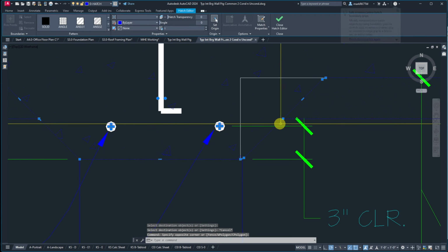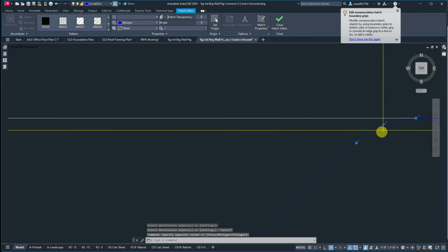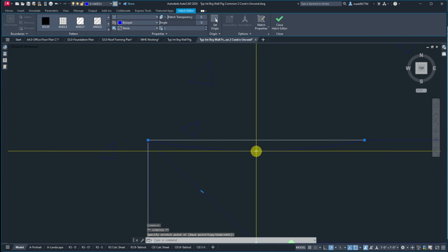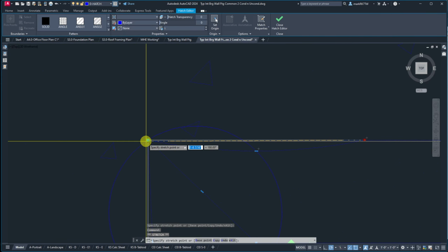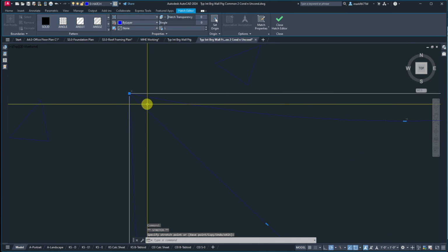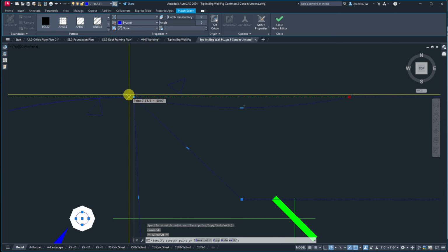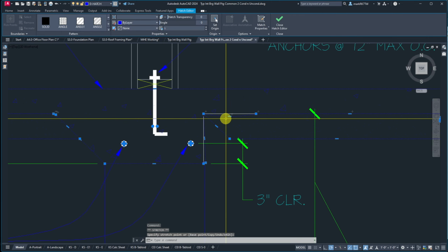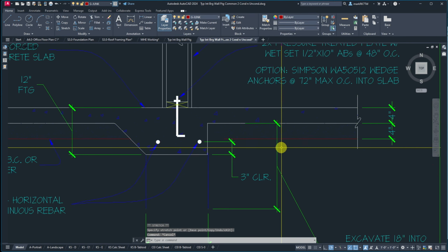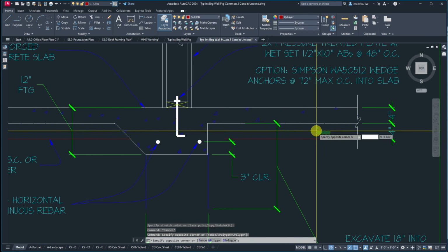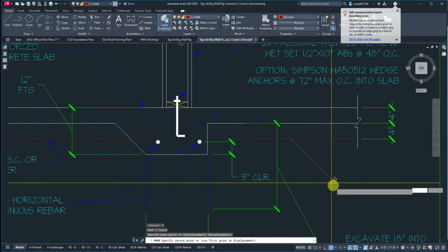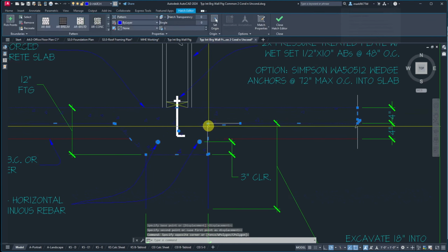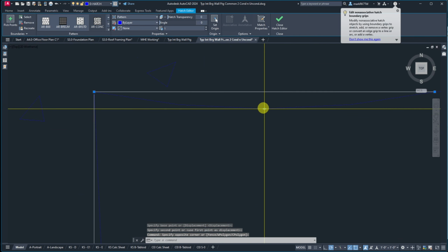Now let's see if we can edit this. Okay, it looks like it was actually made into a, see in the circle stuff, it may not allow me to stretch this. So if you can't get that to do what you want and get rid of that circle, see how it's not behaving, then just like I did with that other stuff, grab this type and move it. And that's why I keep these red lines here that are on the junk layer. They don't print.